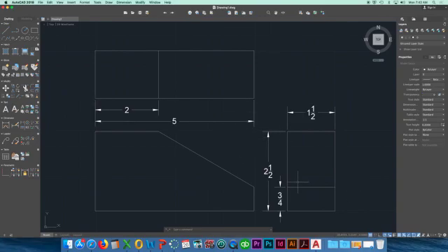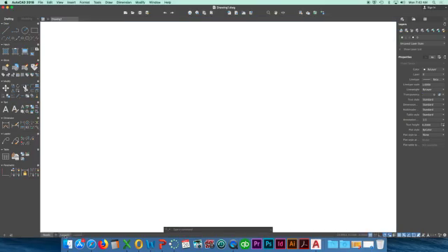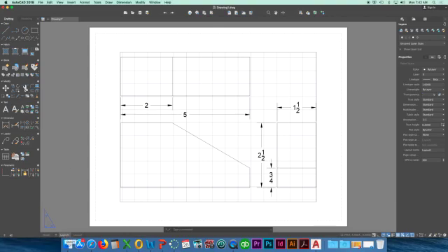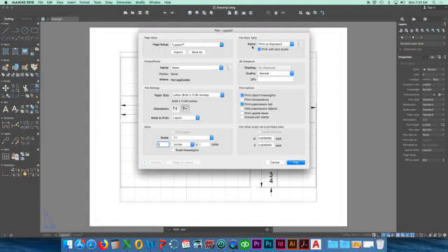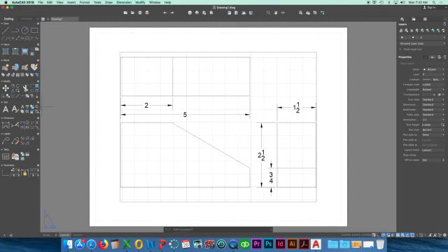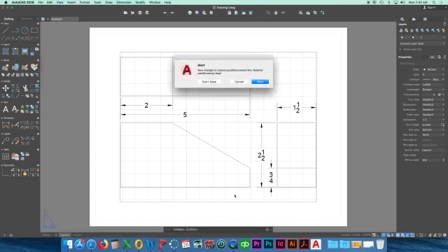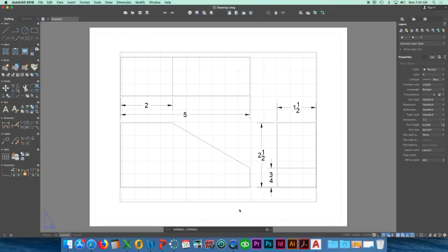Now once you finish drawing it, our next thing is to print it. So over here on the bottom left where it says Model, you click on Layout 1, and it shows you your drawing, and you go File, Print. Make sure you're going to the color cube. So I want Page Setup, Printer, Color Cube, and then I print it out, or plot it out. Once it prints out, put my name on it, put it into a plastic sheet protector. You're going to wait until you get all 3 done before you turn them in with your rubric. And that is how you do CAD drawing.